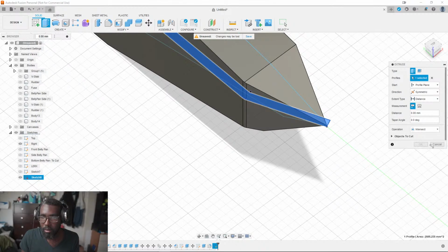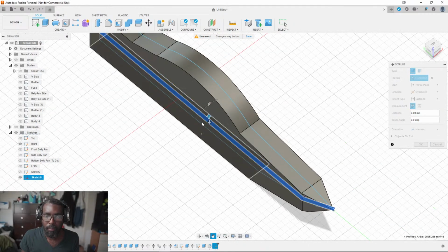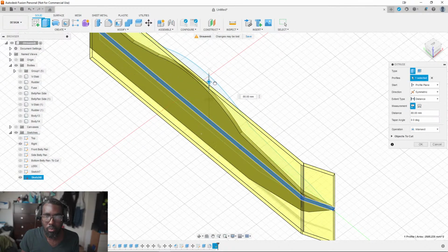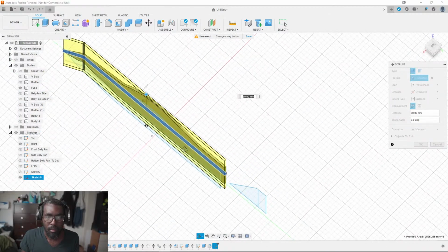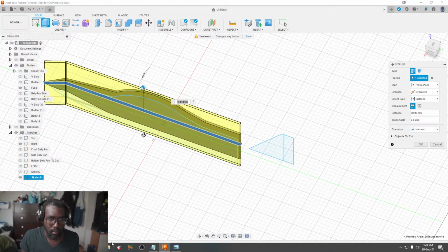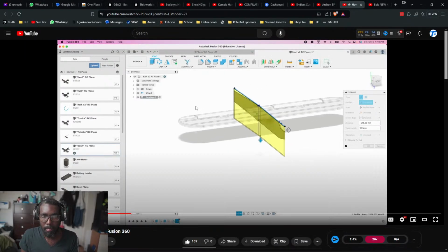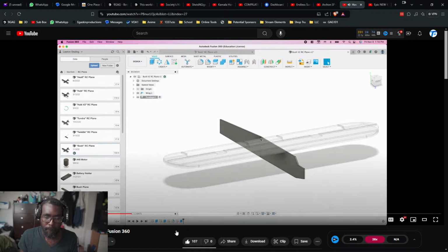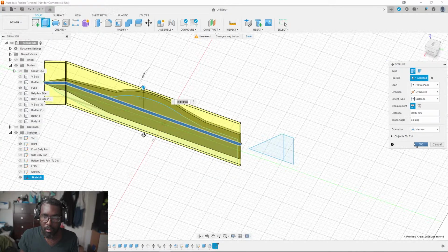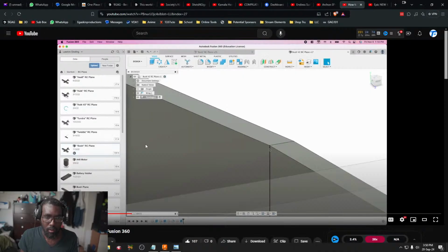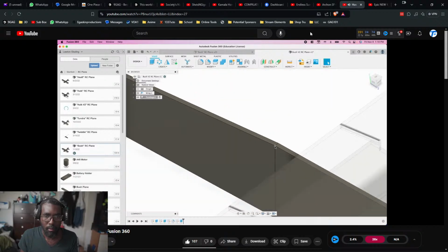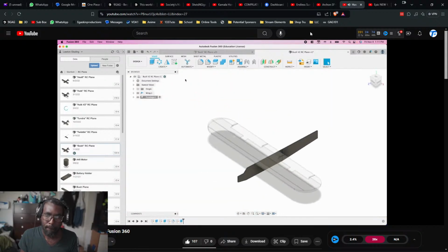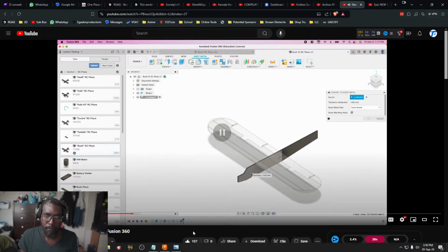What's this? Intersect. Alright, what intersect does is along this plane, it's going to grab, and then you'll see it should have added, yes, just a tiny little curve. Hopefully that's enough that the sheet metal tool can recognize this and flatten it out. And for that, same deal as before, we say convert to sheet metal.